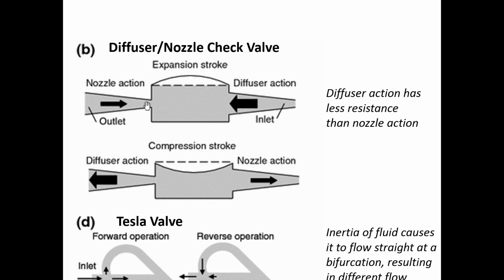Okay. Now this type of thing is well known. It's been studied analytically. It's also been studied experimentally. So again, let me just repeat that since I was a little unclear at the beginning. As fluid is going through a channel, if that channel is expanding, if it's getting wider, then there's less flow resistance than if the channel is contracting into a small point.